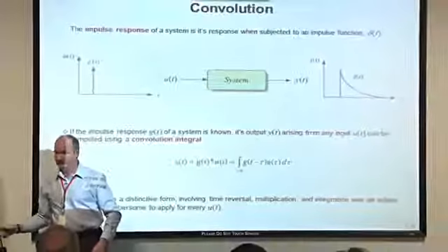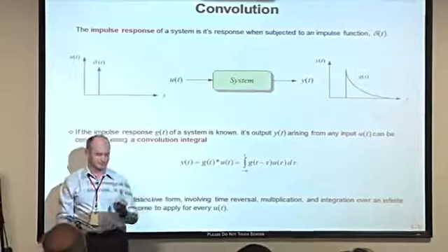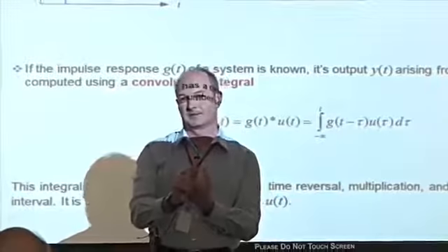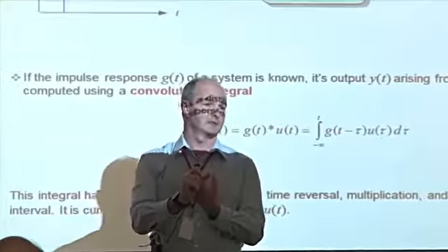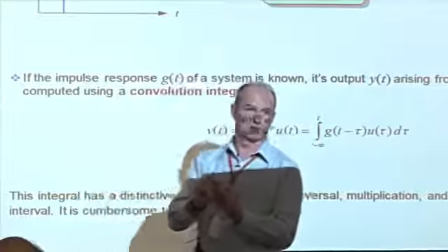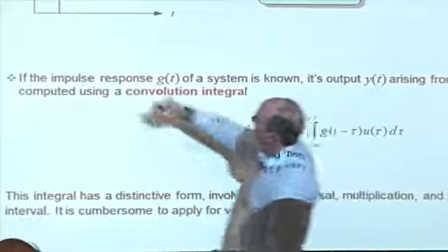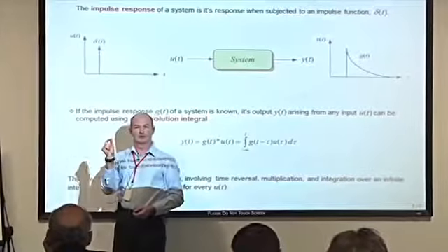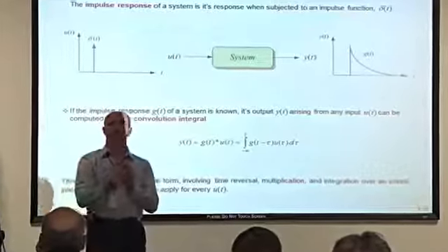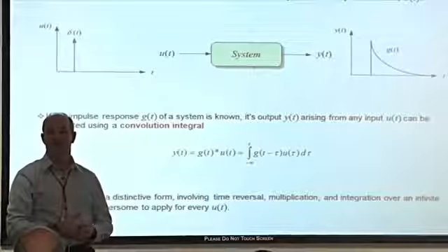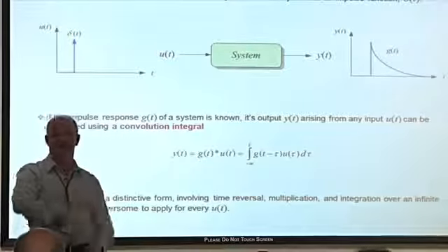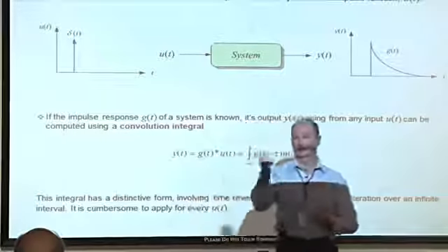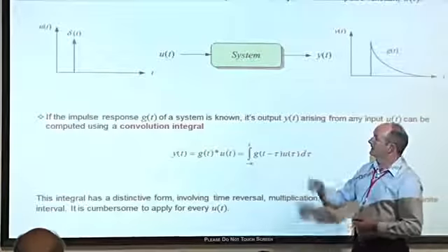Now, the delta function has four important properties that we're going to need today. First of all, it has infinite amplitude. Secondly, it has zero width. And you'll notice already that those things make it very difficult to draw, right? PowerPoint or on the whiteboard is very difficult to draw something like that. So what we do is we draw a vertical line of height 1 with an arrow on the top. The reason it's height 1 is that its third property is if you integrate this function, you always get the answer 1. The fact that it has zero width doesn't matter. Its infinite amplitude is enough to make its integral equal to 1. The fourth property we need, I'm going to tell you about this afternoon, just to keep you in suspense. That'll be enough for now.